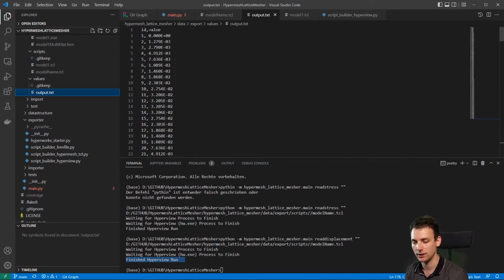And you put each element, depending on where it is on the spectrum of your stress values, into the corresponding bin or basket of your material data. I think that would be a great idea, because then you have a finite set of material bins or baskets. Maybe not every one is filled, but if you have large models with a large number of elements, this will give you a significant speedup.